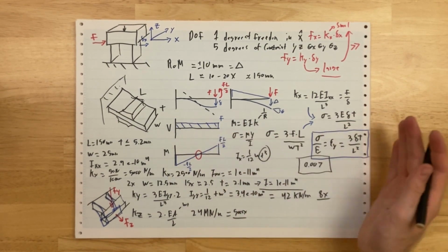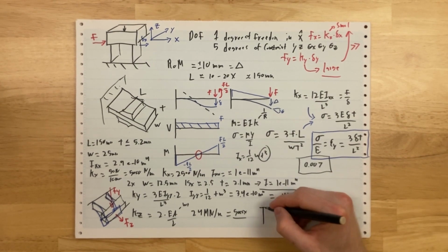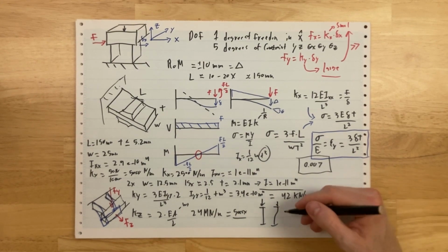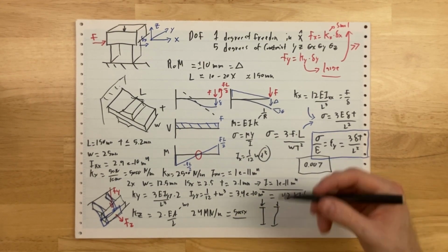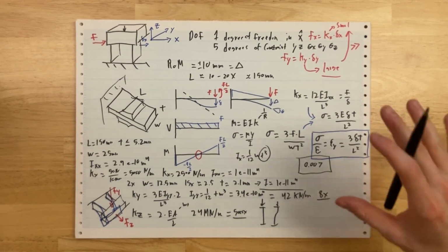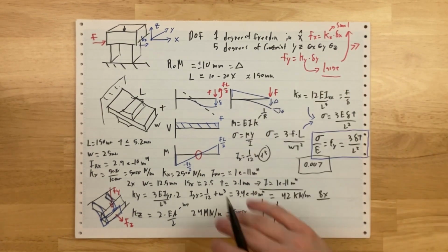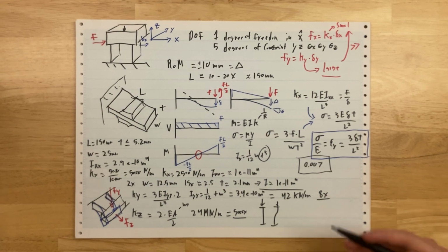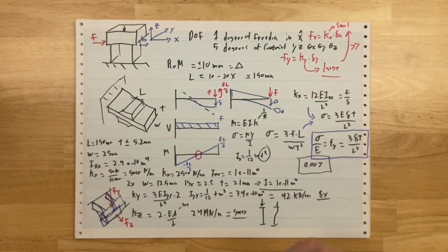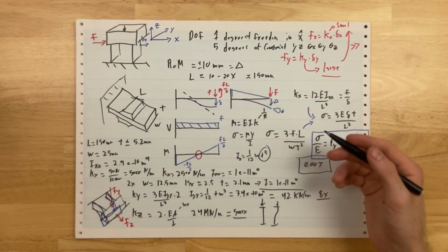However, as you deform the system and push it in x, it's pretty easy to push on a column that's straight, but once you've put an eccentricity into the column, the buckling stiffness starts to fall off a cliff. So does the z-axis stiffness. So you start to get into all these interesting parasitics. This is just enough equations to get a system to work, but if you're a precision engineer, you need to go a level deeper and figure out what are all the other things that the system is doing that I don't like. And you'll find that z-axis stiffness varies with x-axis travel. You'll find that buckling stiffness or buckling capability varies with x-axis travel.